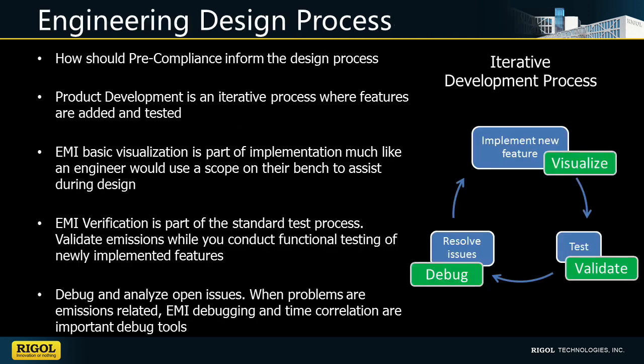So let's take a look at EMI measurements in the context of an engineering design process. Here, let's think about a basic iterative development process where engineers implement new features, test, and then resolve issues. With EMI pre-compliance measurements, we can use basic visualization, just like you'd use a scope on your bench when you're building and designing out these new features.